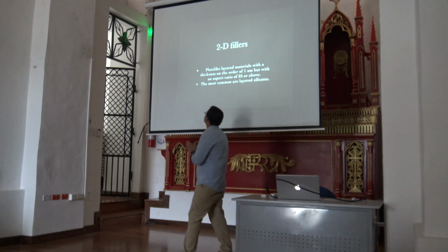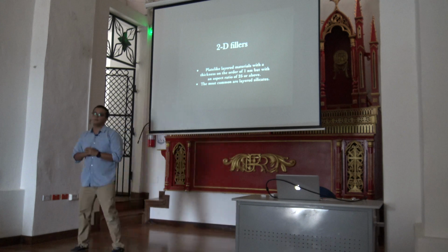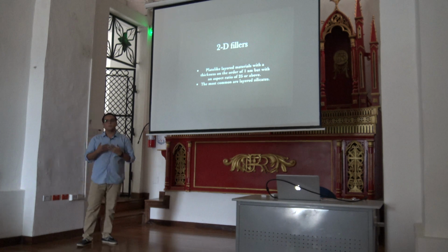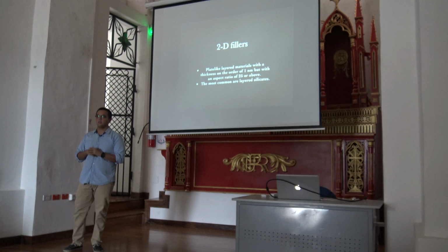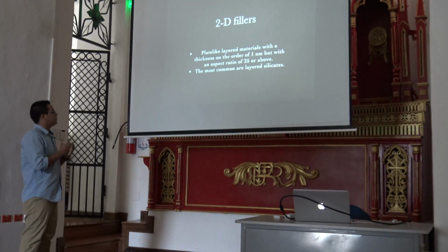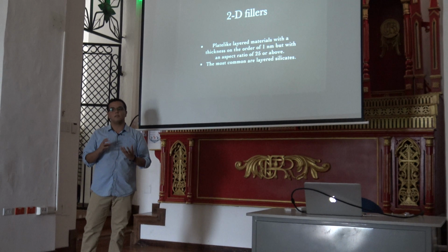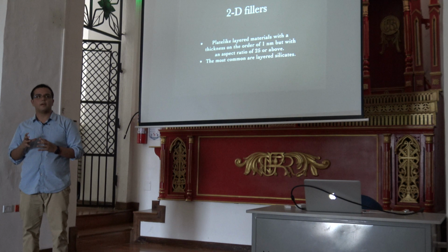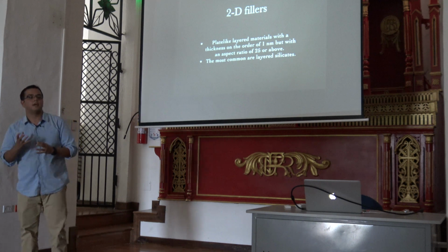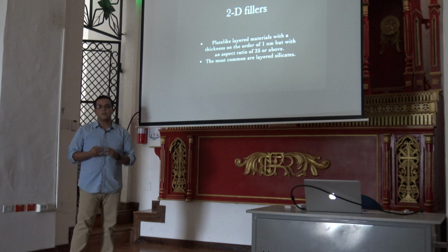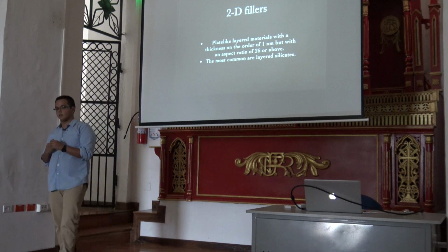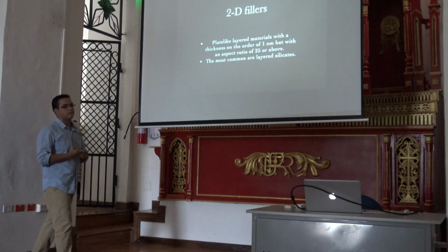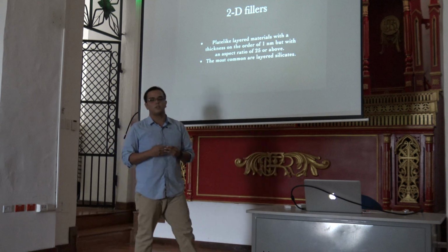The third one is the three-dimensional nanofillers. They are the plate-like layered nanofillers. The most common are layered silicates, for example, montmorillonite nanosilicates. The good thing about these fillers is that when they are in contact with the polymer matrix, the properties can achieve enhancements such as UV resistance, gas permeability, increased stiffness and strength, and also a superior flame resistance.